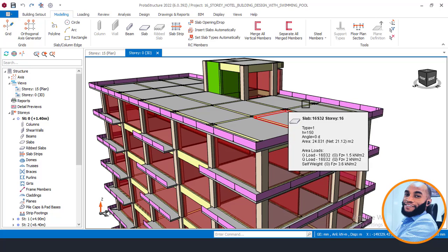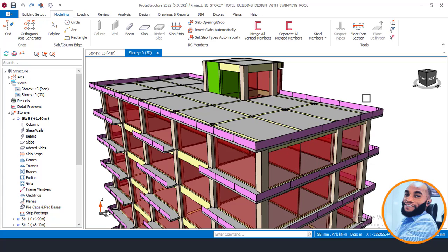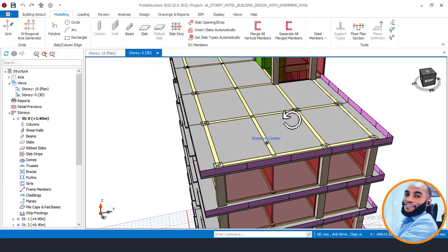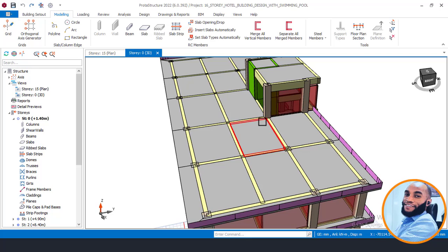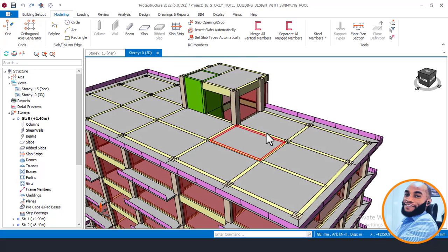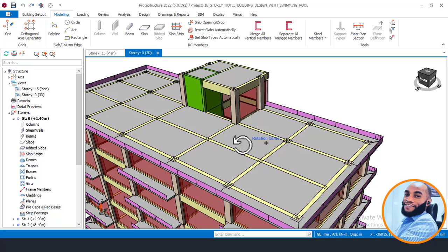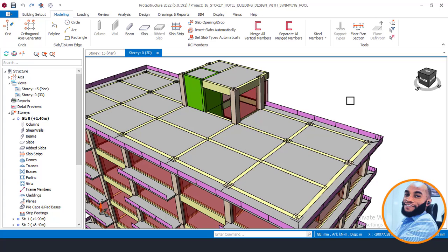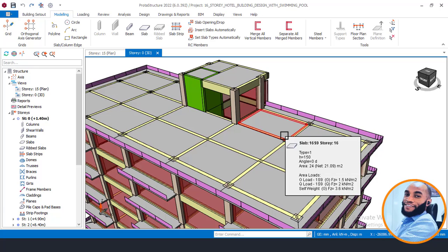But when it comes to live load reduction, or when you want to reduce the weight of your structure, the type of slab that is best considered is the rib slab. Now, rib slab comes in two types. They have one-way rib and two-way ribs. Two-way ribs are often called waffle slabs, and waffle slabs are very good when it comes to live load reduction. Also, waffle slab is good when you're designing for a very large span of a slab.